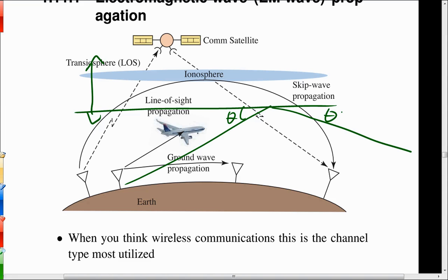So the reuse of all of the spectrum: AM radio stations in Chicago and New York and Los Angeles all share the same AM broadcast band for their talk radio. But if they are all going to clobber each other at night because waves can travel so far, that's no good, right? So the FCC, Federal Communications Commission, says that only certain stations can stay on after sunset for that reason. And they're the powerful stations that are heard around the country with the right antenna.